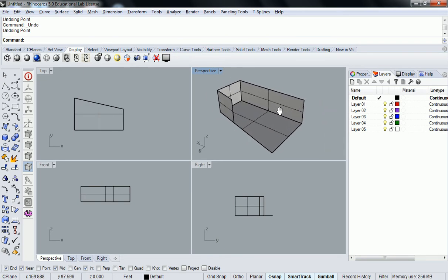Patch is pretty versatile, but you also have to be very careful about where you're placing those points, right? Because control is very important. And when you have a warped surface like that, it gets very difficult to see where you're trimming and where the gaps are between your rectilinear forms and your warped surfaces.